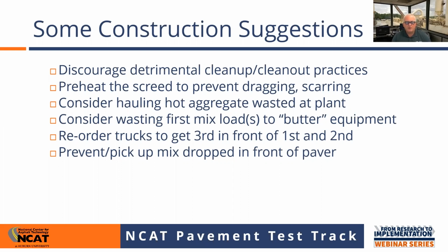But we need to pick that mix up. We need to do what we can to keep that mix from getting on the roadway. If you drop mix in front of the paver, that mix is going to cool down very, very quickly. And then the mix that you place over it is going to have to heat it back up again. If you look at that with an infrared camera, you're going to have a cold spot right there. And that is going to be a place where you can potentially have some performance issues down the road. You might think, well, that sounds extreme, but that kind of attention to detail can really have a positive effect on the performance of that mix out into the future.